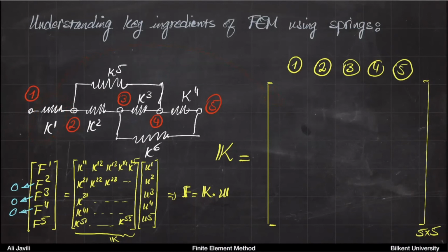But you can also come to this point and see which elements are attached to it. Okay, so at node, or at point 3, or at node 3, you have 3 springs attached to it. At point 4, you have 3 springs attached to it. At node 2, it's also 3. At node 5 is 2. Does that make sense? So basically, you can do it also node-wise and then play with that.